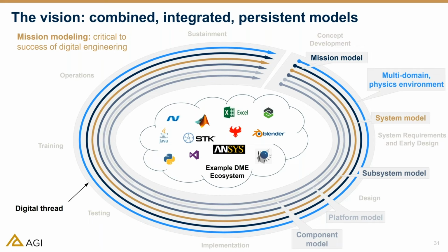So we demonstrated a beginning part of this process in today's webinar, where we looked at some of these tools and applied that to a satellite constellation design. So we quickly built a mission model in STK, integrated it with an Excel cost model with ModelCenter, and ran some cost versus performance architecture level trade studies.